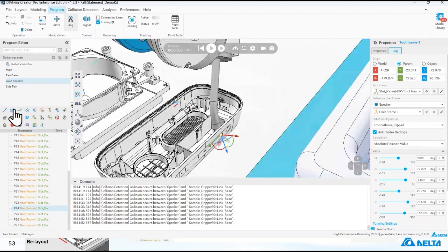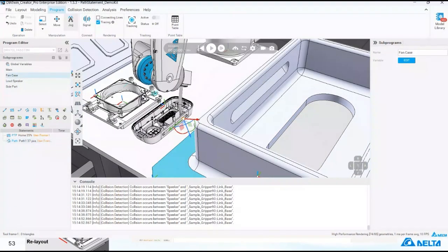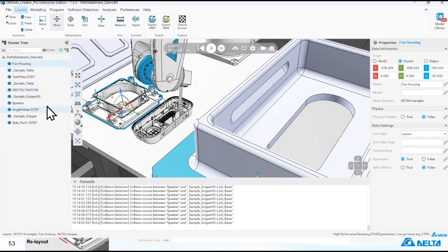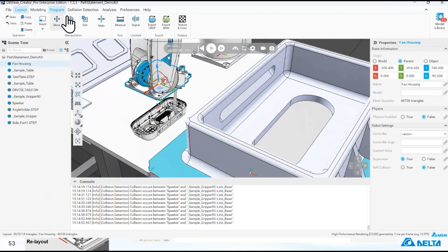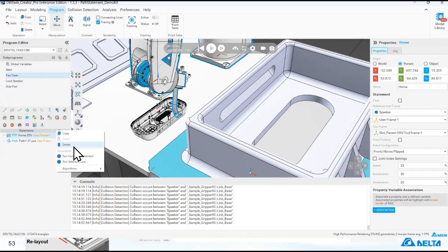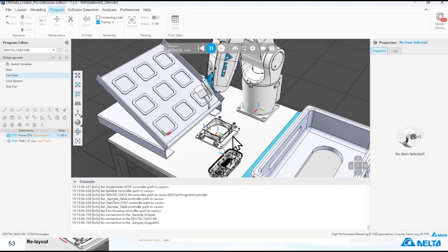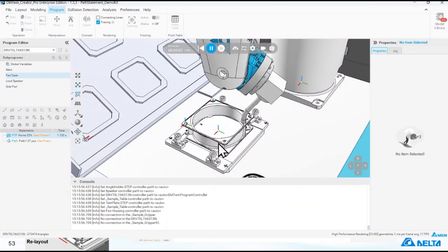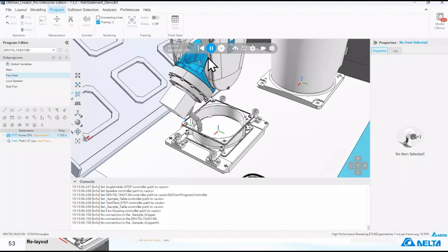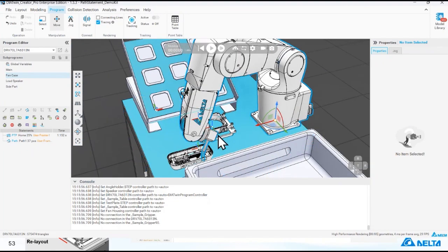For example, if I have a bank case over here, and I want to modify the position and run the bank test, we don't have to do anything else, because the system will detect the user frame on the product to give the right position of the robot. Okay.